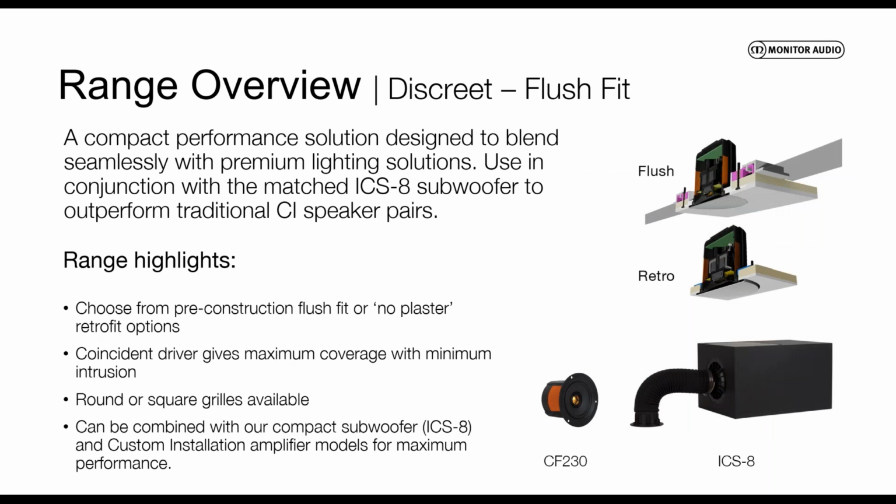So more into our interior design-led products here. This is a more recent addition to our portfolio. This is the FlushFit range of speaker. So we do a great little 3-inch driver speaker, little coincident driver, which gives a great spread of sound from its size. These can be installed either in a pre-construction fashion, so you would fit a mud bank, a pre-construction type bracket onto the surface before it is skimmed with plaster, and then once that surface is complete, when you fit the grill onto this in-ceiling speaker, the grill front is absolutely flush with the surface. You don't get any of the showing of grill shadow or anything on the ceiling, so great for an interior design point of view, matching it with lighting installations, that kind of thing.